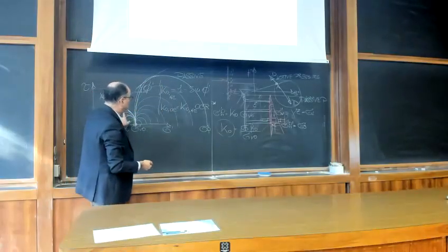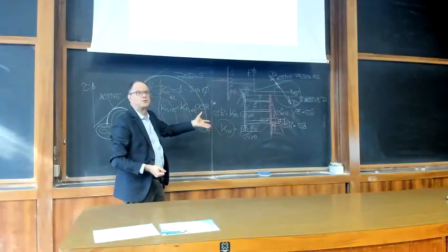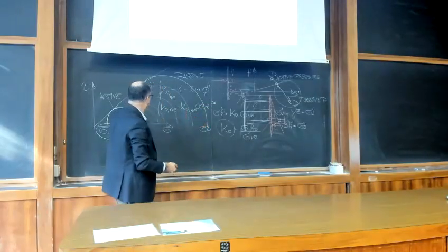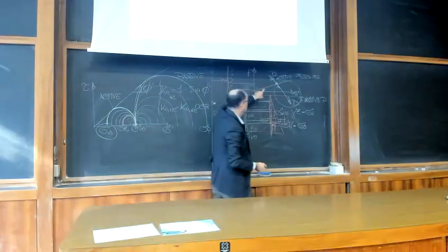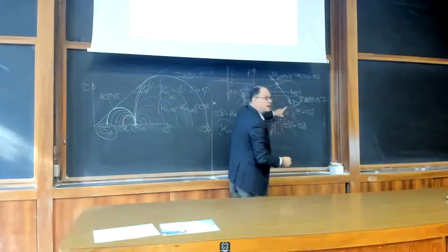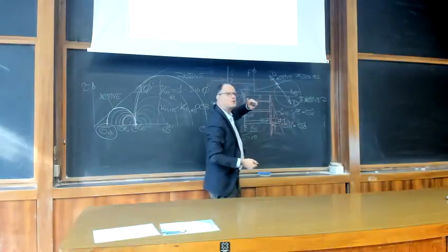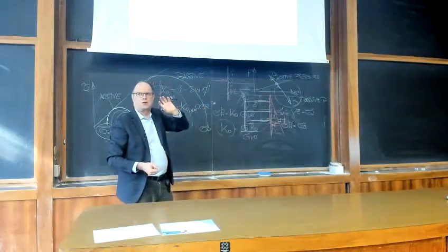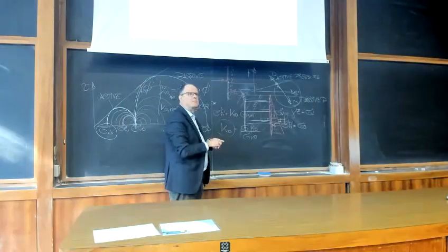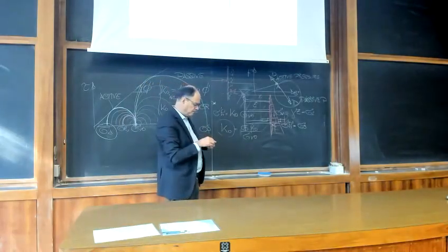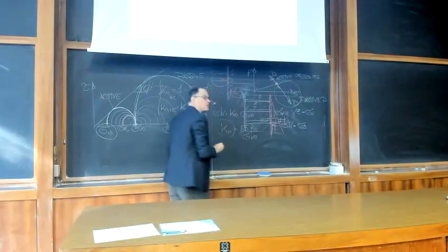Now, if we get to the final failure circle, this is not granted, but still the load path of the soil here is more like that, whereas the load path of the soil here is more like that. So you see the tricky thing of soil behavior, even for the basic requirement to know the actions acting on the structure.